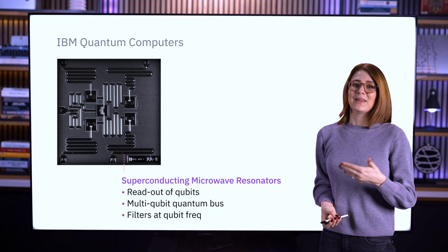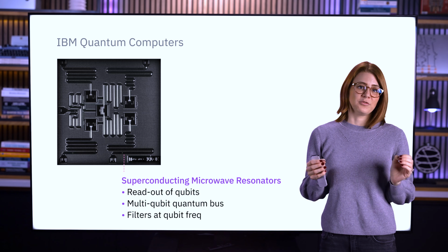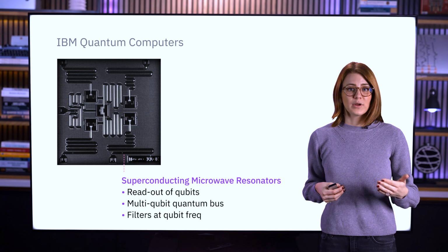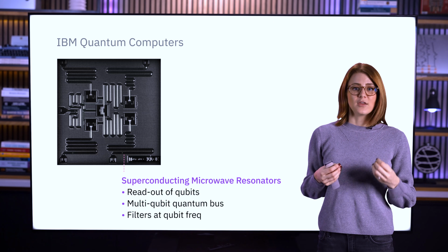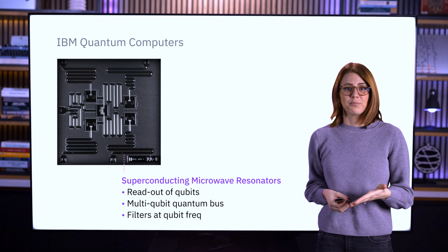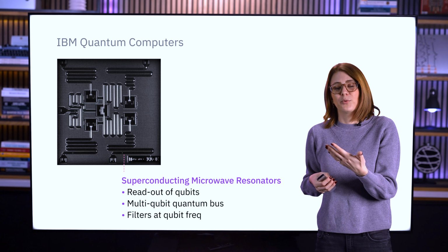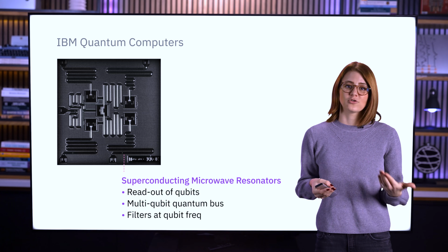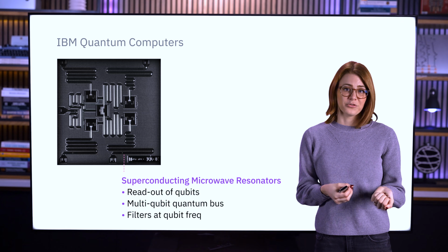Now, when we program a gate, that essentially equates to choosing a highly calibrated microwave pulse, and the specific frequency, amplitude, shape, and duration of those pulses make the qubit do specific things. The instructions for the microwave pulse go from your computer to the cloud and then are read and interpreted by room temperature control electronics, which take those instructions and physically generate the pulses.